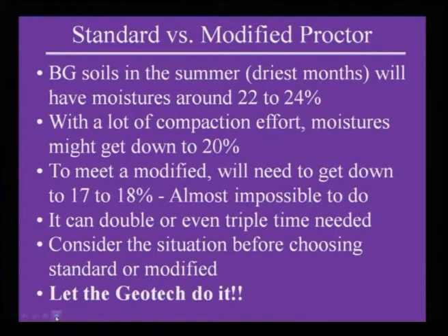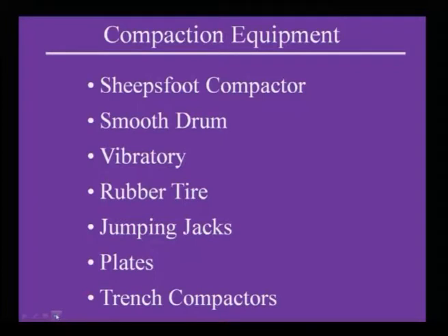So, you decide first where you are going to use it, where it is required, and what purpose the compaction is for. If it is a simple building, simple field, then you go for standard. If it is a complicated one, then maybe you can choose the modified Proctor test. Now, what are the compaction equipments?